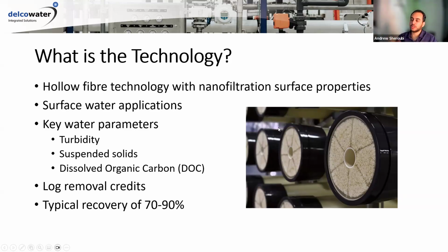This is in the same technology, versus, as I said before, where we do ultrafiltration or some other pretreatment followed by RO and NF to get everything that we need to. In certain applications, we could just use one technology. However, it is newer, and thus the membrane elements are a bit more expensive than either a UF or RO and NF system. So the cost is going down as more and more membranes and systems get installed.